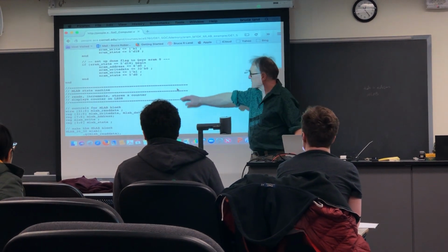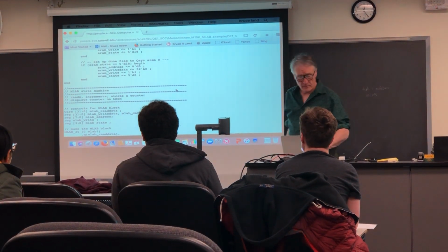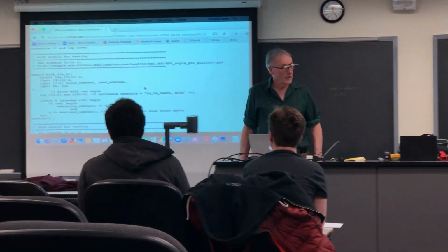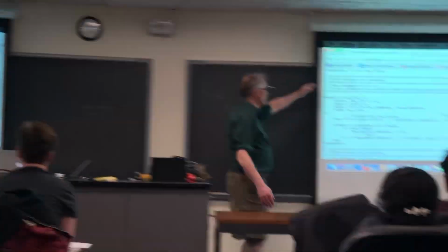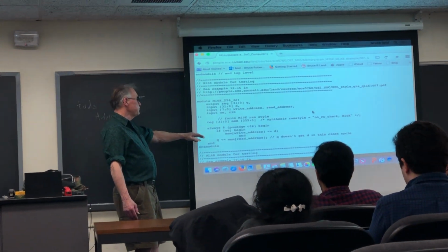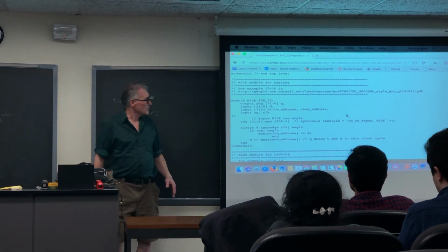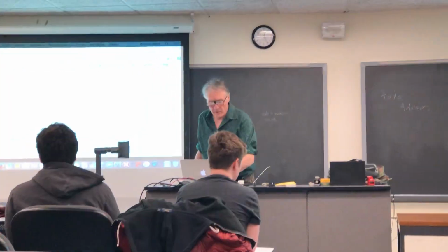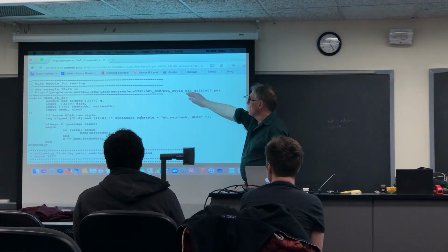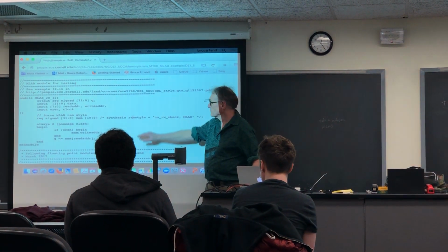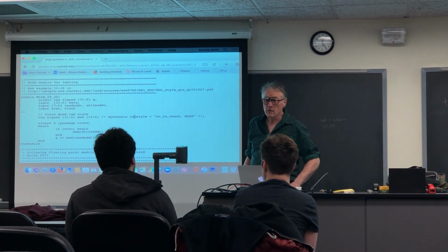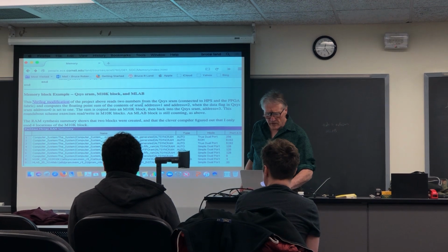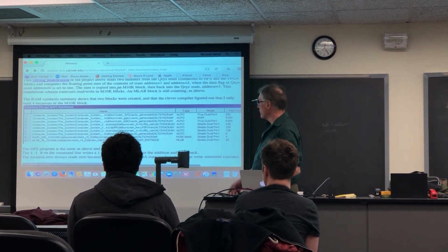You'll find an MLab state machine to read and write MLabs. And then towards the bottom of the file, you'll find an M10K module definition, simple 2-port, and an MLab module, which instantiates correctly.